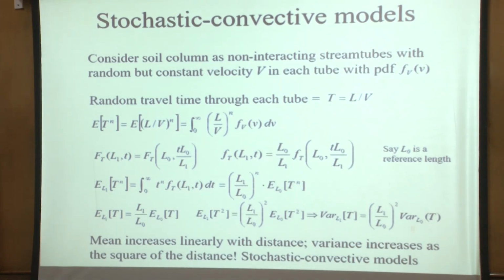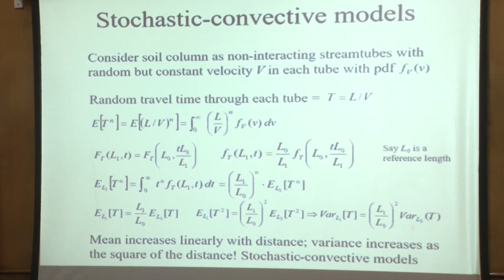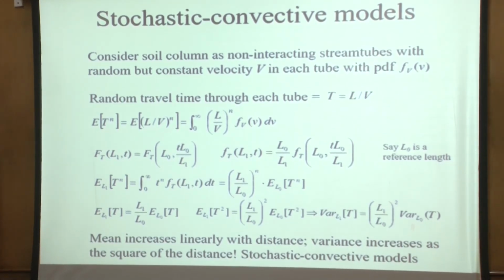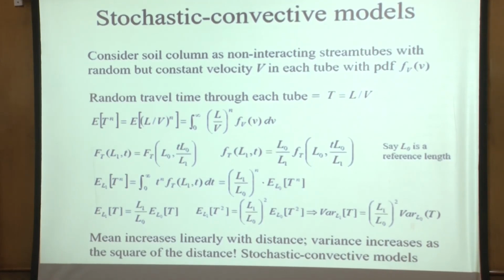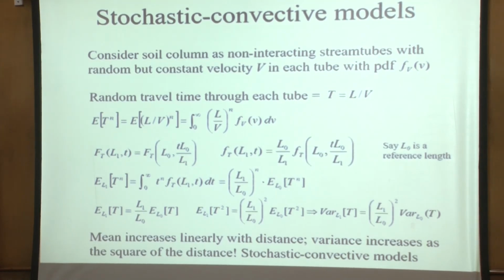There are two different ways of thinking also. This is something that we do in fluid mechanics, but in fact, it's actually the same thing. We talk about Eulerian and Lagrangian approaches, right? And they come from different considerations. So it's the same idea actually, the same difference fundamentally. The advection dispersion equation uses control volume, it's an Eulerian approach. The travel time distribution, each particle is being tracked individually, it's a Lagrangian approach. Okay? And therefore they're going to be different. They're not going to be behaving the same way. So the question about why you think one should have a different variance.